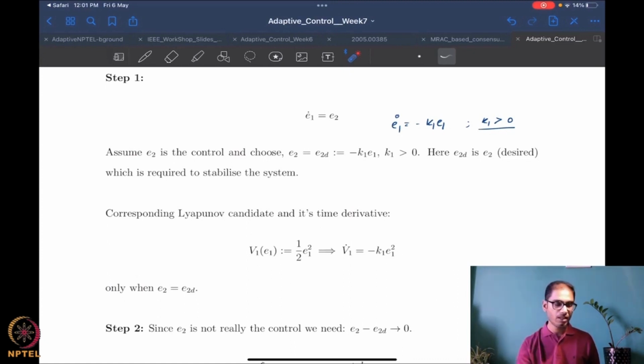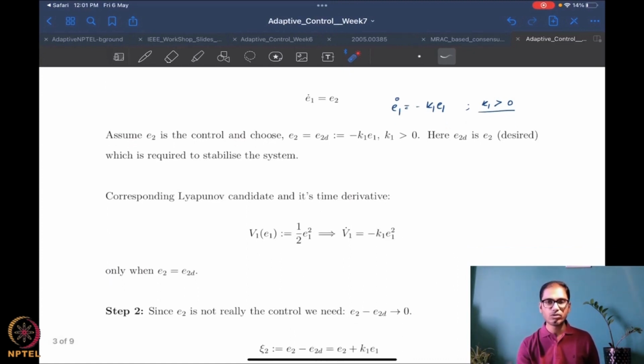Yeah. Great. Now, we of course also introduce a corresponding Lyapunov candidate function. Because honestly speaking, backstepping is a method of generating Lyapunov candidates by augmenting one piece to another piece. Okay, it's actually not a method of control design, but a method of generating candidate Lyapunov functions. And as you might have already seen, we are by now used to designing parameter update laws, and control, using, well, I mean, not the control yet, but the parameter update laws are being designed using a Lyapunov candidate.